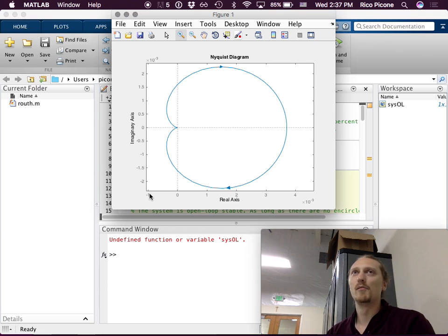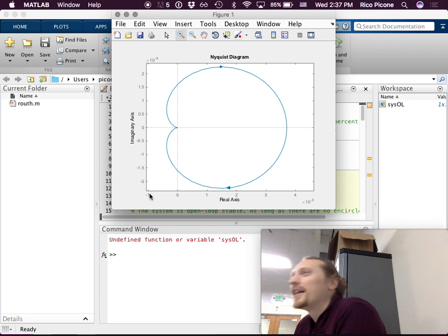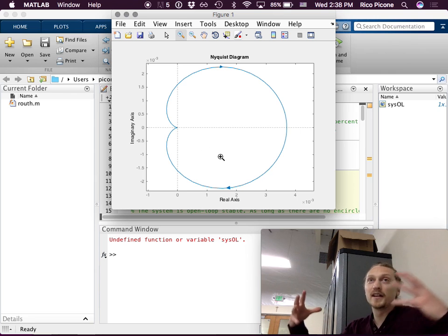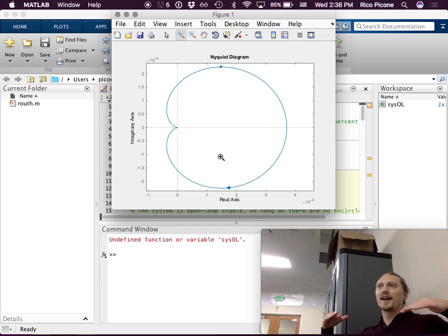If we have a giant gain, couldn't it possibly cross? That's right. Exactly. So that's what this initial convenient gain is going to be about for us. We don't have this. So if we scale this thing up, then it will eventually leave the unit circle, and then it will come back. So that means that we will have a phase margin that's defined. So if we increase the gain, we'll start to have a phase margin.